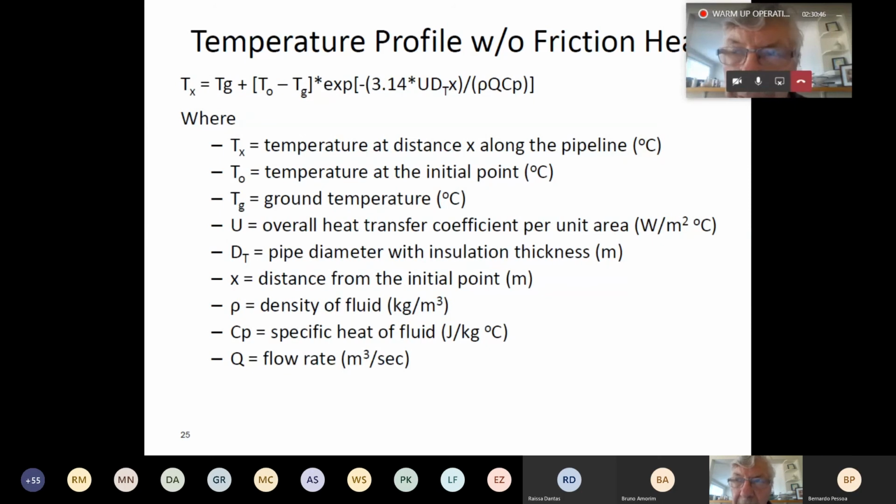And that's one of the things that's very interesting about the difference between pipelining natural gas and flowing oil. Because as you know, with oil, the warmer it is, the easier it flows. For natural gas, it's the reverse. The warmer the gas is, the stickier it becomes, and so it's harder to pump. And that's often why in hydraulics for natural gas, immediately at the pump, as the product comes from the compressor, we put it through coolers to cool it and therefore reduce its viscosity. So it's one of the interesting things about the differences between oil and gas.